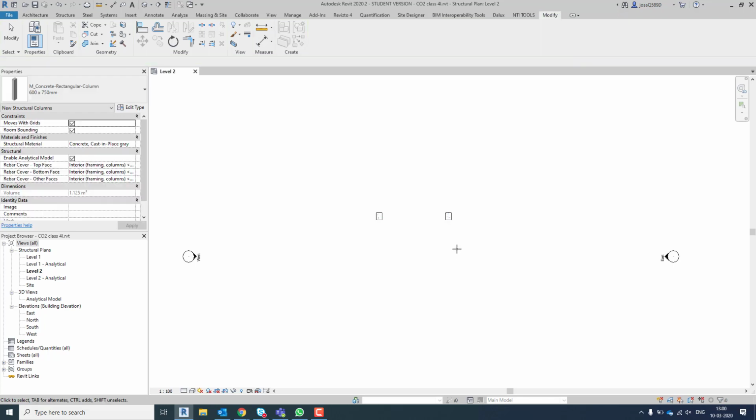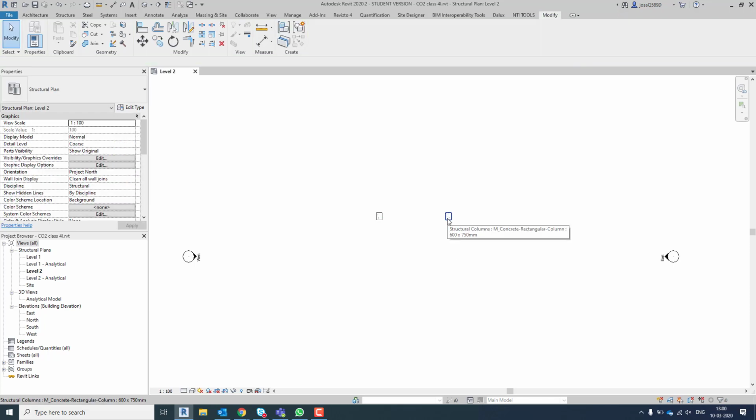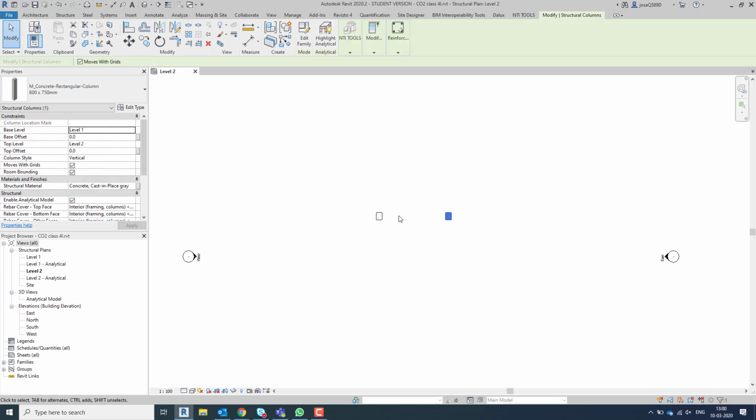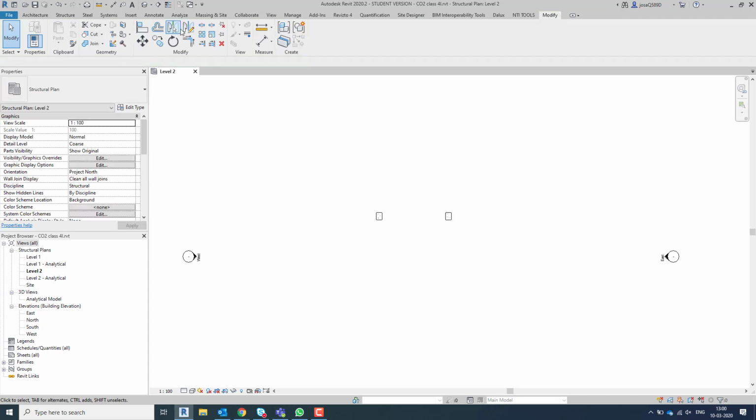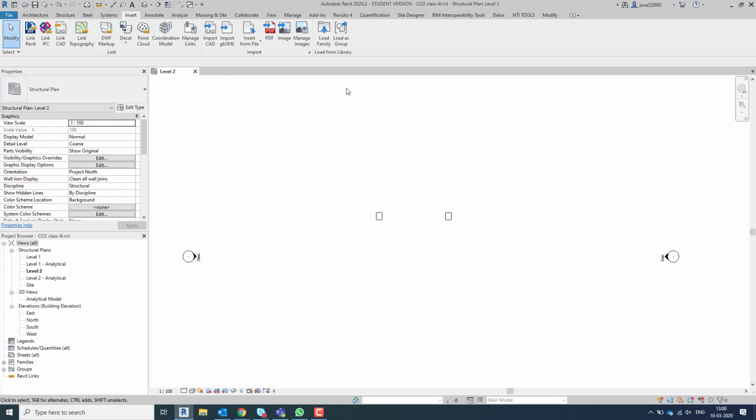We're going to change the second one to be another family, so we need to be wood, right? So what we're going to do, we're going to click on it. No, actually no. Let's go to insert. And we're going to load the family on the insert tab.